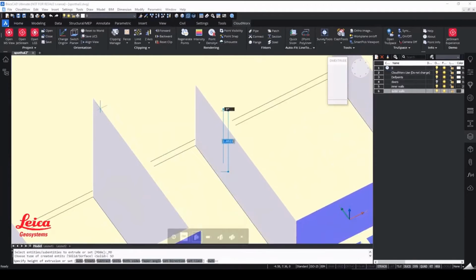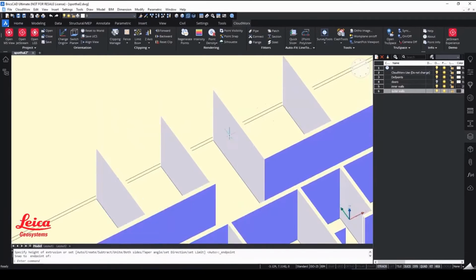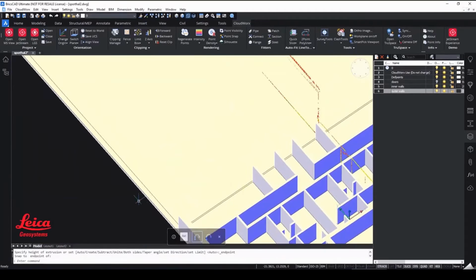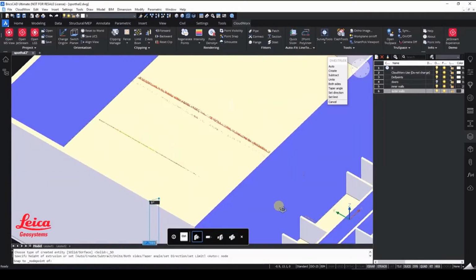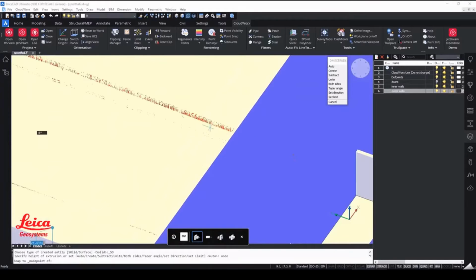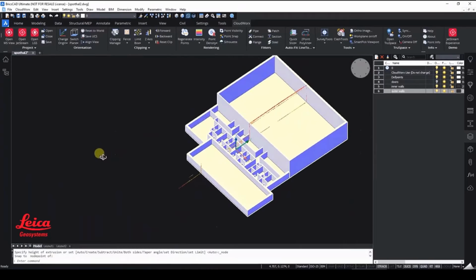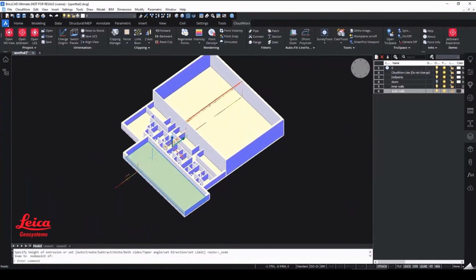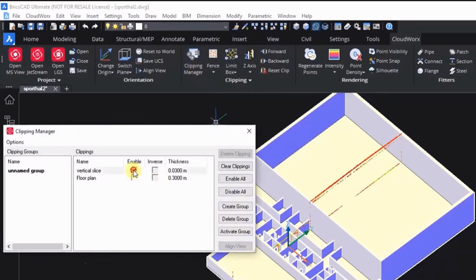And obviously we've got that big area of the sports hall at the back that we can also potentially use as well. What we've done there is use the prior model as the height, and then we're just setting the height for that sports hall area as well, again using the point cloud to specify the right location. And you can see the model is beginning to take shape, and this has all been done on the basis of our reality capture data.